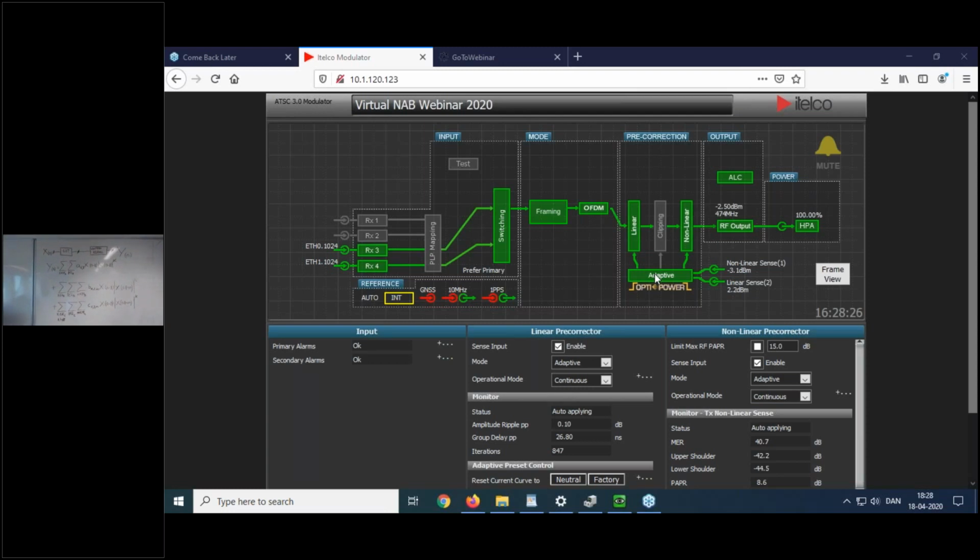The wonderful thing is that this framework is so well functioning that I have not had to rewrite the precorrection ever when we meet a new waveform. It always works. It always works with any transmitter, Doherty, class A, B, or whatever. So that investment in a lot of mathematical effort in the beginning has paid off really well.